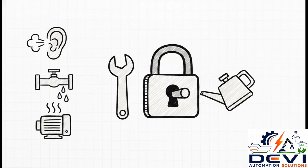If you're working with pneumatics, honestly, a lot of the time technicians just use their ears. You just listen for that hiss of an air leak. For hydraulics, you're looking out for oil drips or watching for a sudden drop in pressure. And for electric, you might be checking blown fuses, feeling for an overheating motor, or inspecting the communication cables going back to the PLC. Routine maintenance is all about lubricating those moving parts, swapping out seals before they bust, and calibrating everything so it moves exactly as far as the PLC thinks it is.